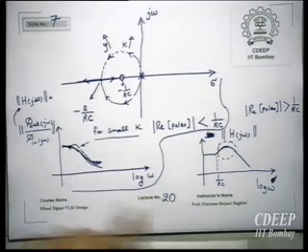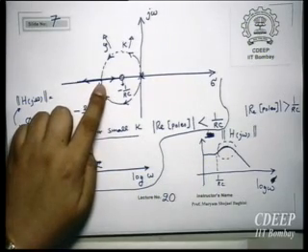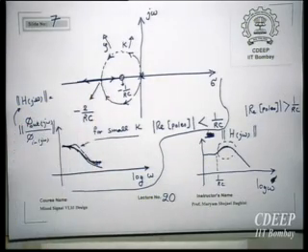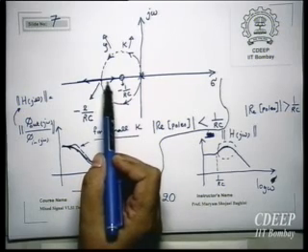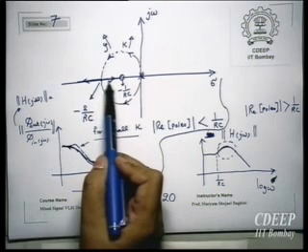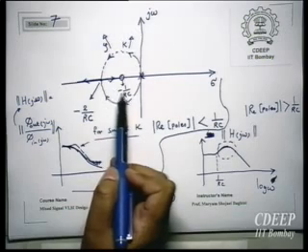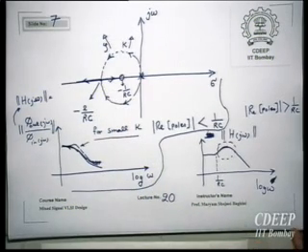So still here poles are imaginary. And then when we reach here, it means that now we are increasing the damping factor, right? When poles are completely real, one of the poles is still here and here also. Still the poles anyway are on the left side of 1 upon RC. Therefore the effect of this 0 will always be first.